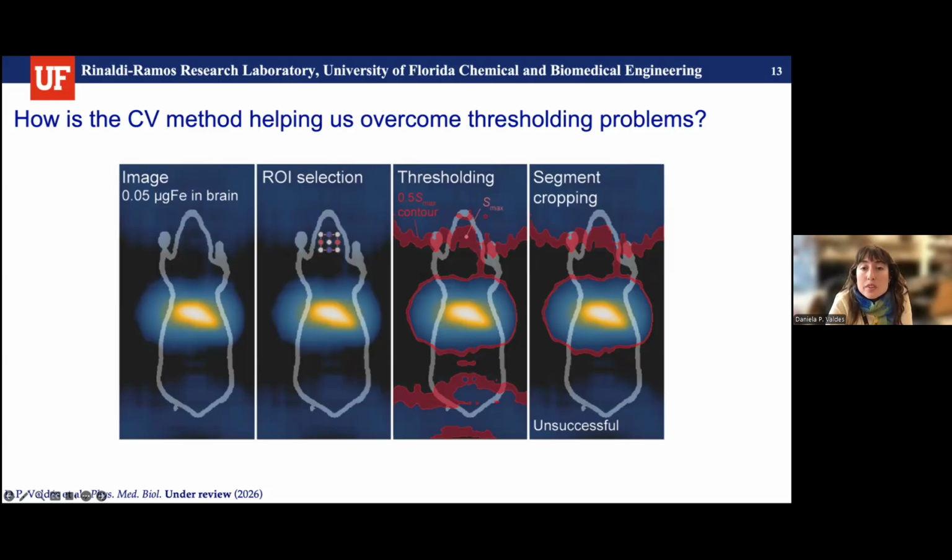And that's the same thing for the reference scan. Then the script has an interactive part where the user can intervene. For example, if the threshold had two different regions, one around the ROI and another one grabbing some values from the background, you can crop the ones that are not connected to the ROI.